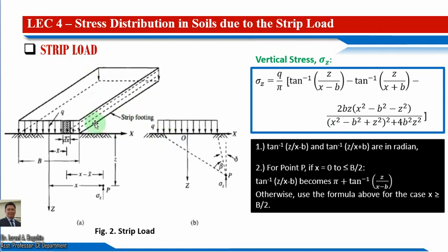The state of stress encountered in this case also is that of a plane strain condition, as for the line load. Such conditions are found for structures extended very much in one direction, especially in the y direction, such as strip and wall foundations, foundations of retaining walls, embankments, dams, and among others.